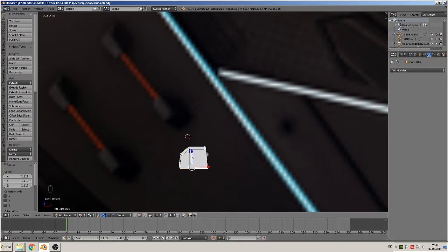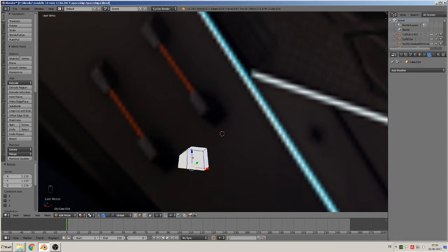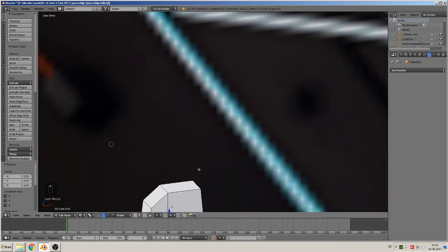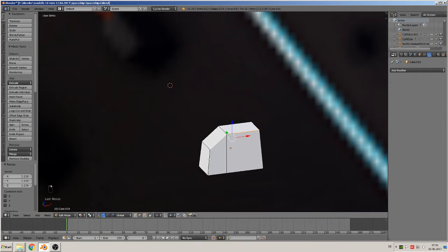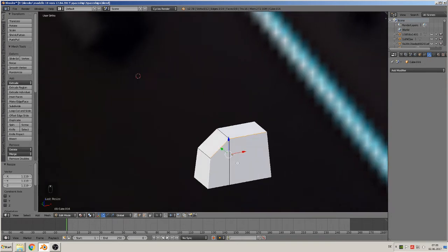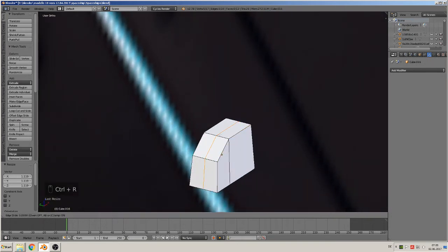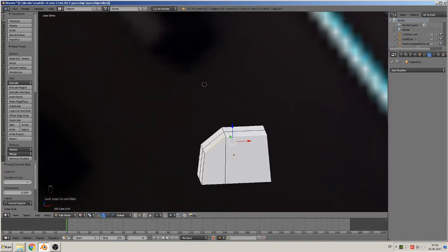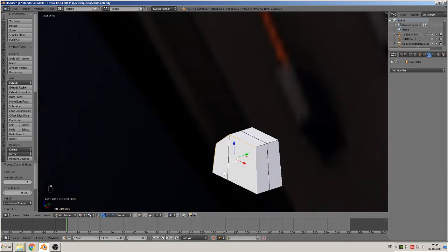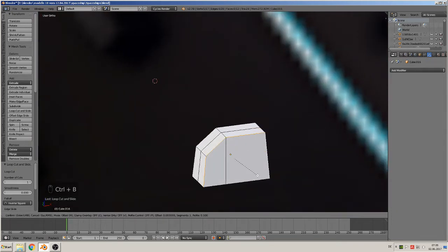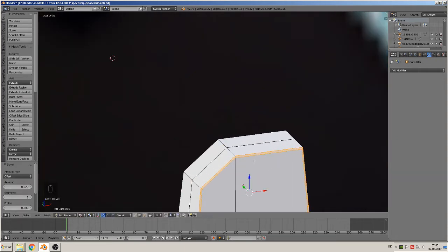Normally you can make here some more edge on them when you say you take that here and give them bevel or something there for the fine detail. I don't know, we need that. I would say no, but we can make it here. So we get that whole thing and then Control B, move the mouse, and we have that little effect there.